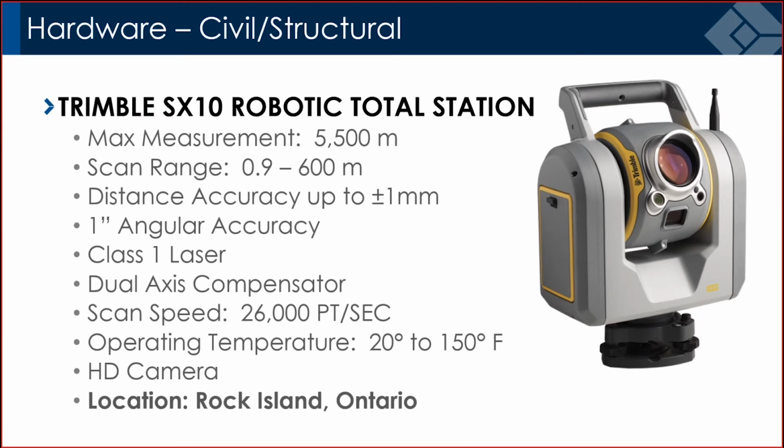The advantage of this is we can use it for topographic surveys, and we can also scan on top of control and incorporate that control outside of the field. It's not as fast as the Faro, but again, it is a total station first, and it is ideal for more outdoor applications. This particular scanner is located in our Rock Island and our Ontario office. Both of these scanners do take high-res photos, and they use those photos to colorize the point cloud.